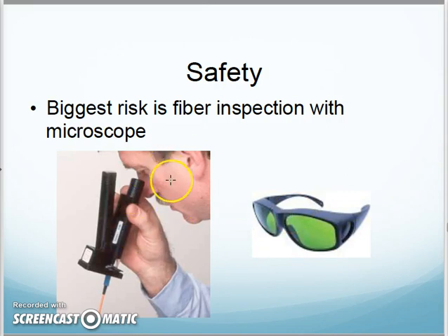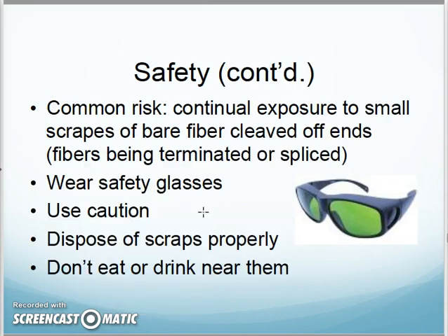But where the problem comes in is if you end up inspecting the terminations with a microscope. Extreme caution must be taken to make sure that the fiber cable on the other end is disconnected, so that you do not have that light source coming through the microscope and being focused into your eye and doing some damage to your eye. So some safety there with light sources in your fiber optic.